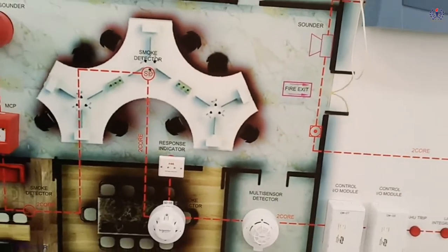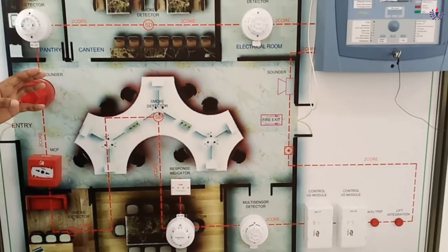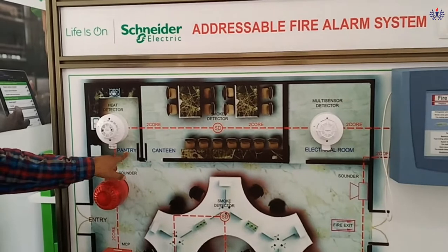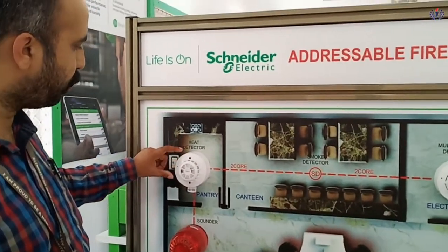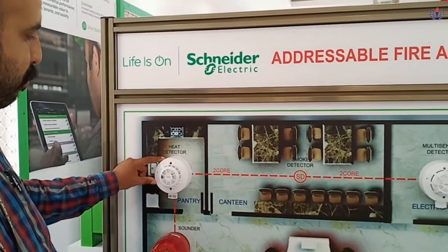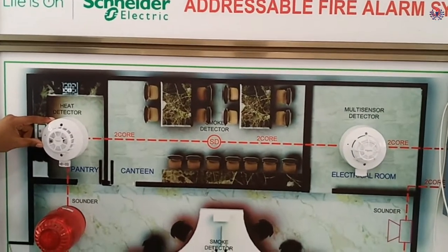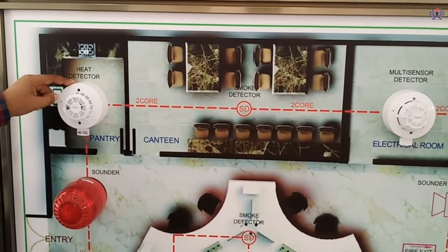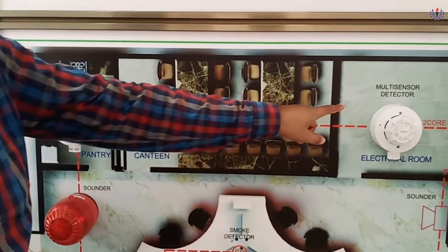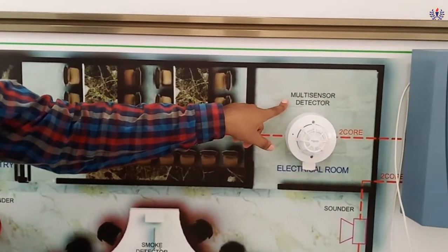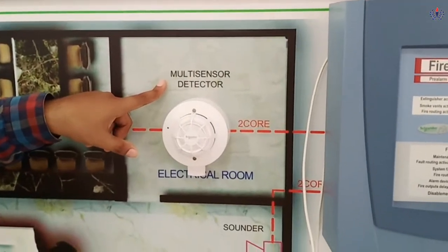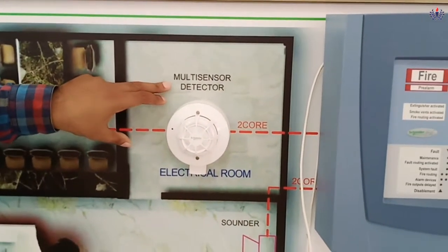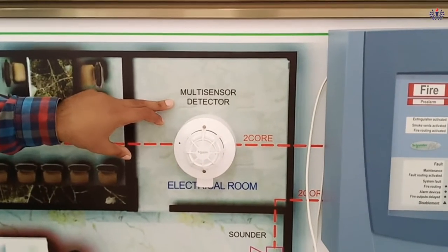In that we are going to locate different types of sensors. For example, in the pantry we are going to keep a heat detector. This is the input device which senses the heat. If it reaches the prescribed temperature, it will work. The next one is the multi-sensor detector. The speciality of the multi-sensor detector is that it can sense heat as well as smoke as well as fire. So three things can be sensed in this multi-sensor.